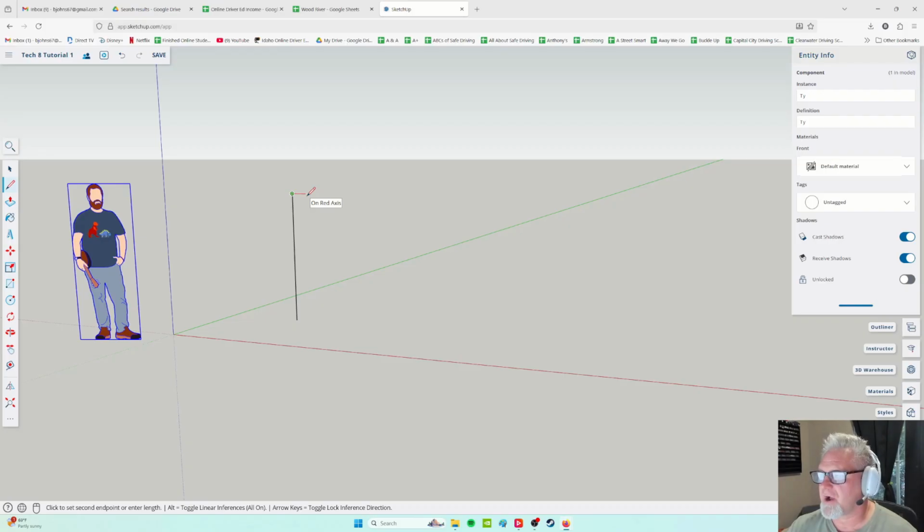Now, I want you to draw, notice that it wants me to keep drawing. Well, what if I don't want to keep drawing? Hit escape. So try that. Hit escape on your keyboard, because maybe you want to start drawing on a different location.